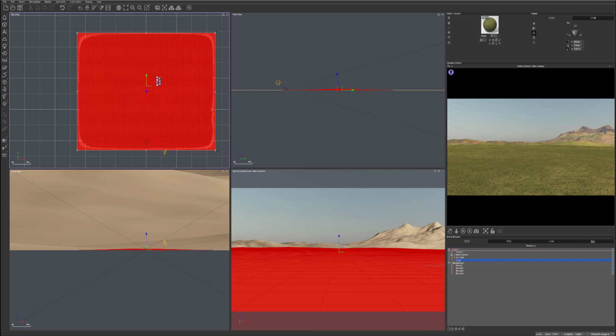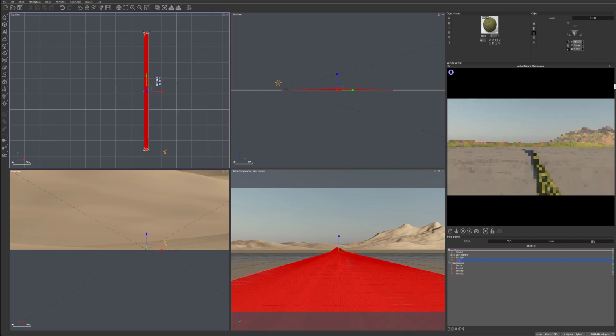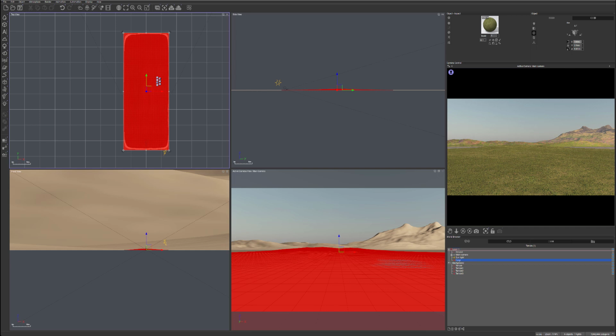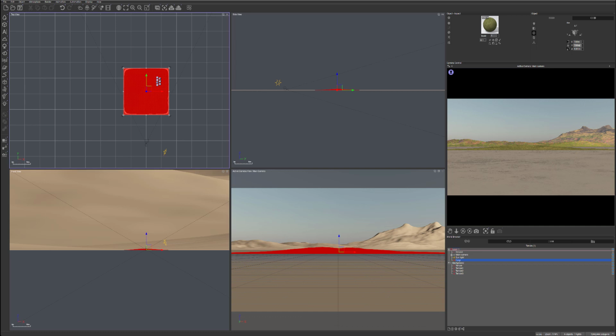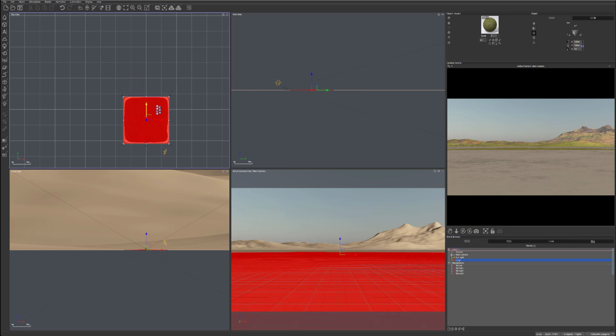And I still think this terrain is a little bit too big. So let's go ahead. We'll select terrain sizes, and let's go down to maybe 150 meters. And the reason why I want to create smaller is so we have less area to populate with the ecosystem. So it's less polygons, will be much easier to work. And I think height is 4 meters, so let's just set 1 meter height on the Z, and we'll take this, bring it closer to our camera, like around here.